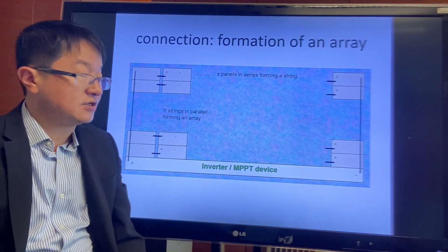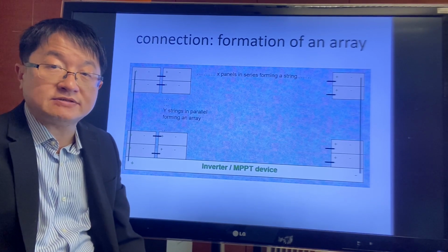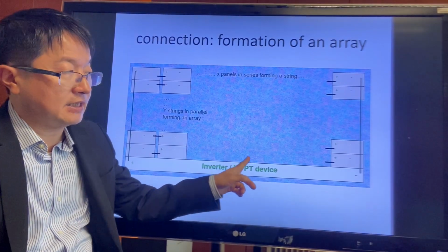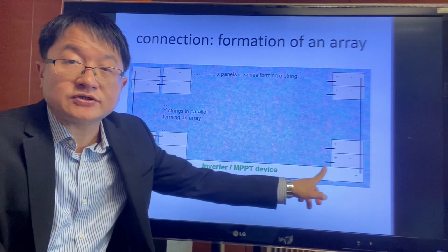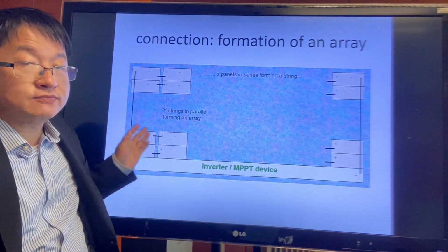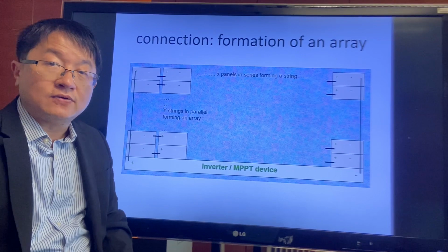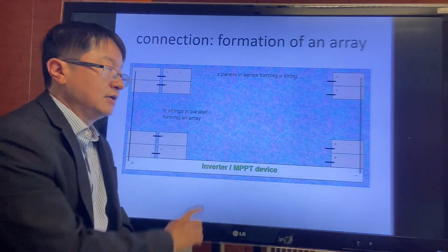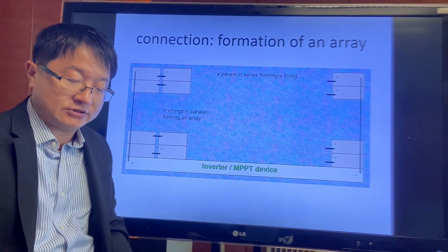Therefore, in practice, we will combine the benefits of both parallel and series connections. All the cells will be connected in series so that they can step up the voltage together, with many different rows running in parallel to form an array, so that even though a single cell is not working, so this row is not working, all other rows can continue the service and provide electricity supply.